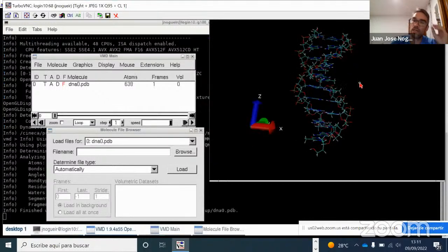So in order to run molecular dynamics with periodic boundary conditions, probably you have studied the periodic boundary conditions in another lecture. The charge of the cell, the charge of the system, has to be 0. Otherwise, the Ewald summation doesn't converge properly, okay? Probably you have studied this in your molecular dynamics lectures. If this is not the case, you can go to our YouTube channel, and we have a couple of lectures where we talk about periodic boundary conditions and the Ewald summation, okay? But anyway, for this tutorial, we don't need to explain it. The important thing is we need to have a neutral system, so we need to add some sodium ions to neutralize the negative charges of the phosphates, and then we are going to solvate the system, okay?